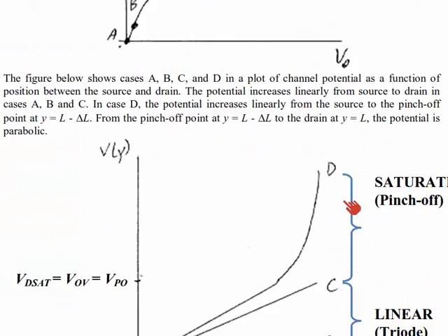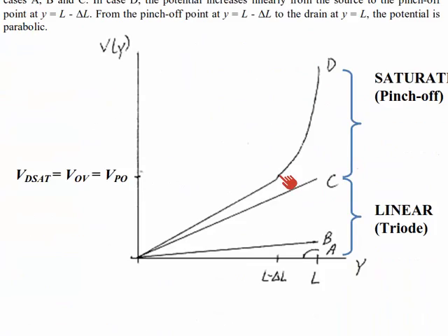As you know, to obtain the potential distribution in a depletion region, we integrate the charge. It's space charge due to the substrate doping, p-type acceptors in this case, for an n-channel FET. And the integral of the constant charge gives us a straight E-field distribution. Integrating this straight E-field gives us a parabolic potential drop from drain to the pinch-off point. So we have that parabola there to drop all the extra field.